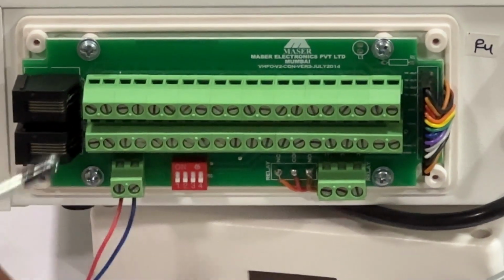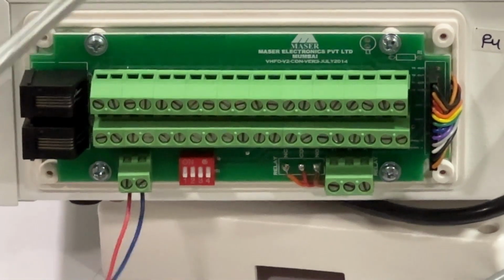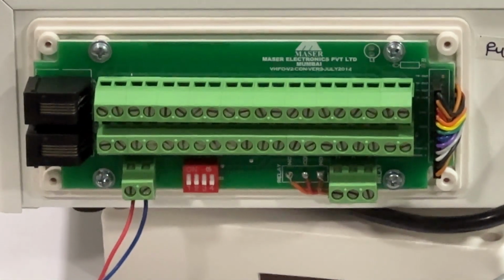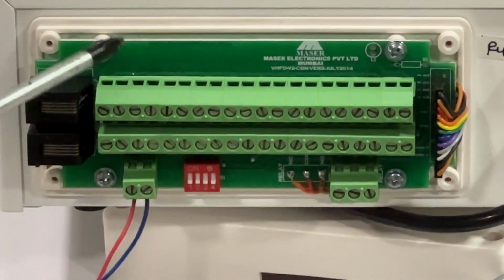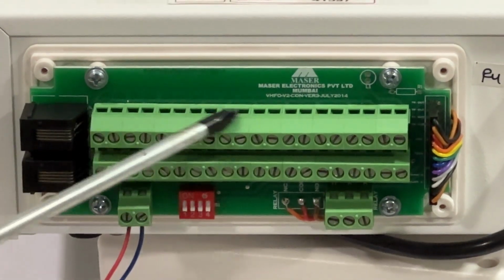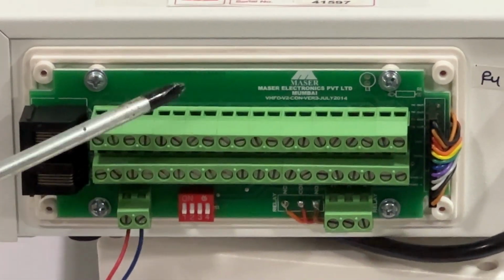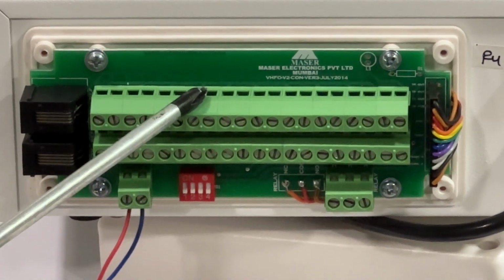In looping, the wiring will be like a loop. If somebody cuts the cable in between, the rest of the transducers will stop working. But in dedicated, if one wire gets cut, the rest of the transducers keep working. So it depends on the client and the consultant's requirement.